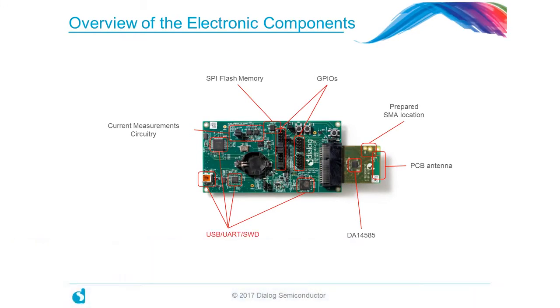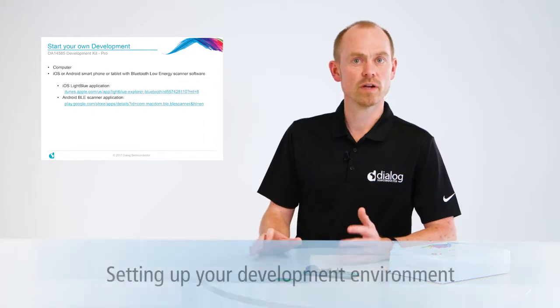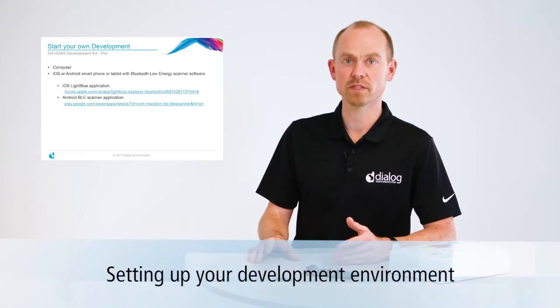Let's take a closer look at some of the most important features and functionalities of the motherboard. A USB UART SWD interface, GPIO connections, SPI flash memory, and the most appreciated and used feature, the current measurement circuit for the power profiling. I'll explain this functionality further on in the video. On the daughter board, we have the mounted DA14585 device, the PCB antenna, and it's prepared with an SMA antenna connection.